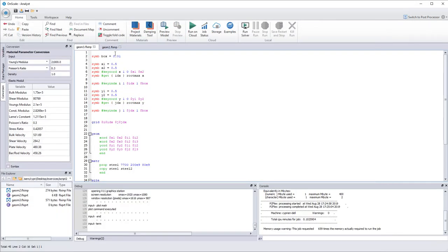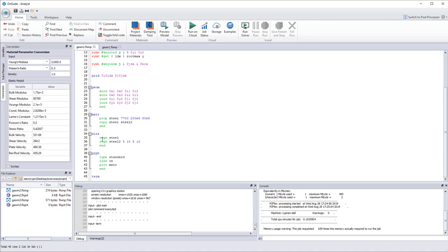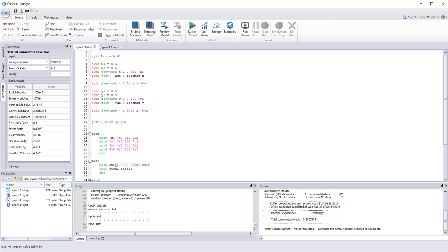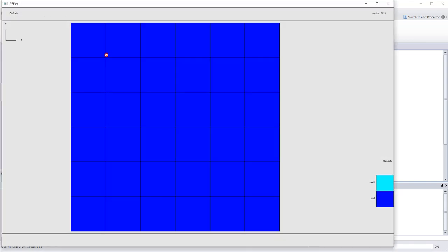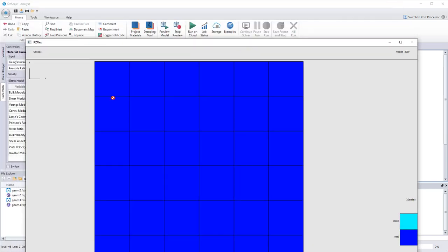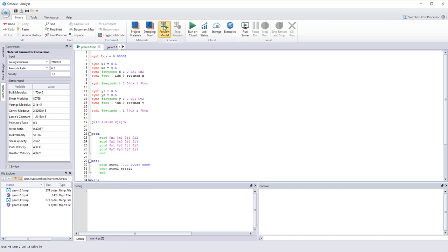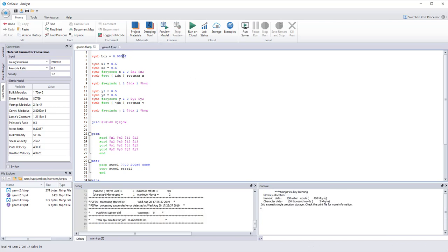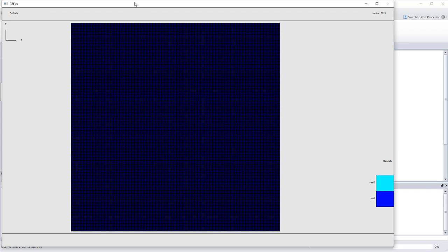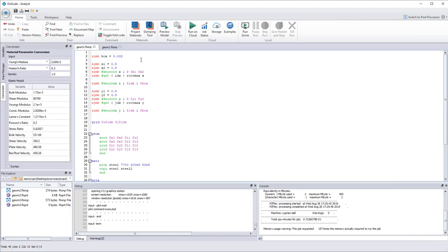Yeah, because if I put 0.2, the grid is too big and I cannot associate this. Well, I could try. So if you want to comment out a function, you can put a comment like that. And now I can try 0.2. I think this time it will work. Yeah. So previously I associated to something bigger than the grid, so it cannot work. And this time this grid is very big, and I can also preview. Oh, maybe this is too small. Okay, very small. Right. So it became parametric. So now I can just change the size of the grid and this will change.